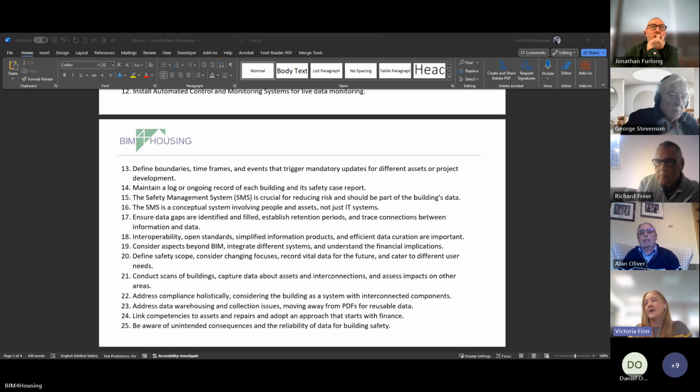So I agree with the holistic view. Look at what else is there. But this is what we're being asked to do, and this is what's also being picked up on the FRAs: to replace these doors. Who's asking you to do it, Bex? Well, I interpret the legislation that way anyway, but our external fire risk assessors are asking for them to be done and asking if they've got bi-directional testing. We've even been asked by the fire service if they've got bi-directional testing, and I know a lot of other RPs are doing the same.